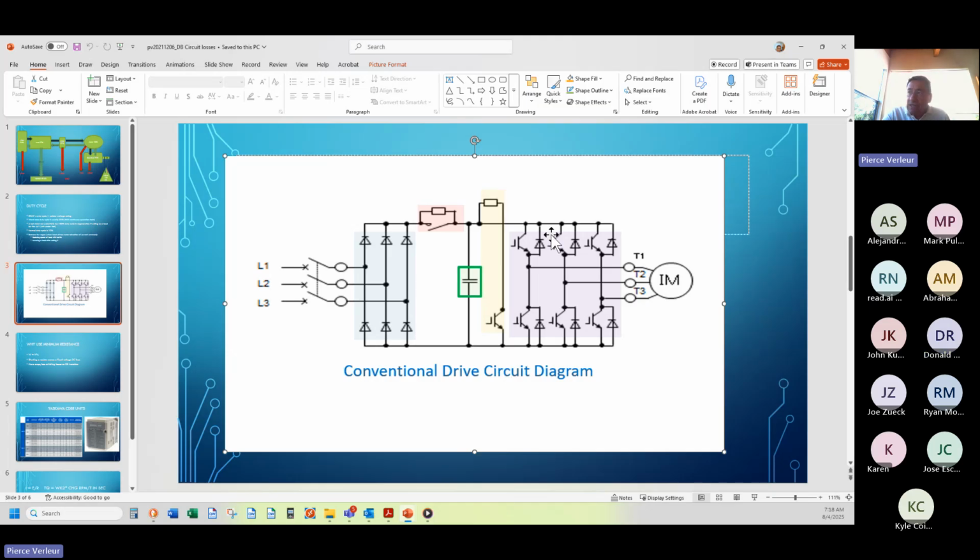That resistor obviously has to be sized to handle the current and the wattage. And the way we size these resistors under hard loads, they're going to glow. That's okay. They're made for it. But now consider this. You don't want to mount this where it's going to set something on fire. And typically on 10 horsepower and above, that means outside of the electrical enclosure.